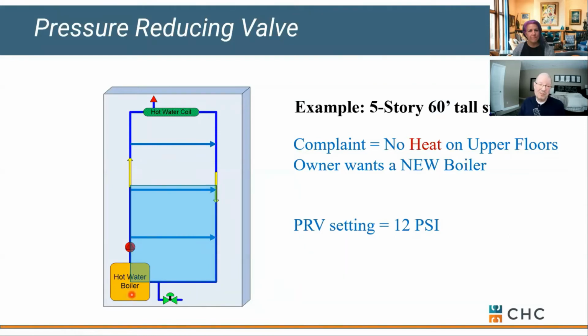To make matters worse on this job, I know they had no heat on the upper floors. They also had a pump that was rotating backwards for 10 years, okay? It wasn't going the right direction. That's not very efficient. So that's the importance of a fill valve.